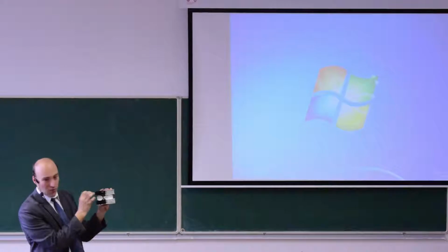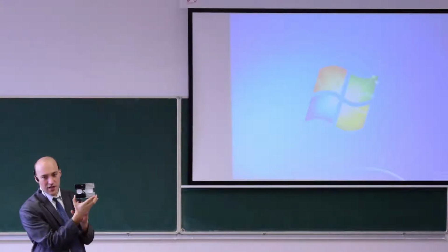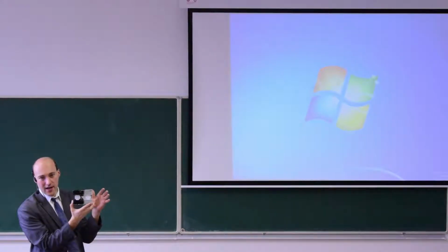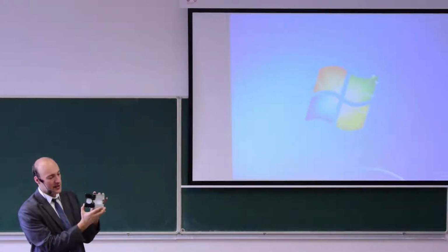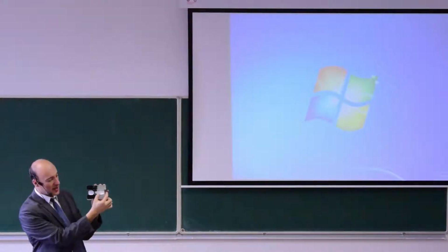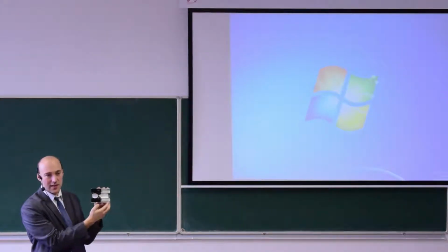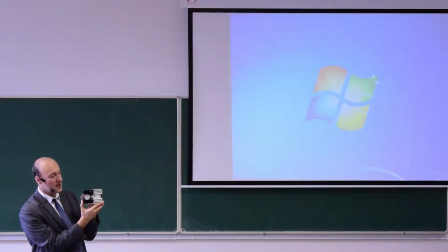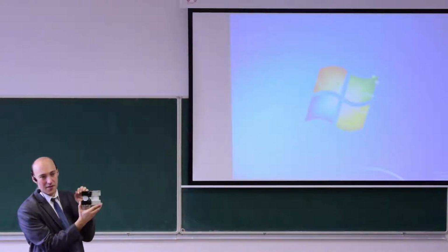If you look with a thermal camera at such a heat sink, when its temperature is higher than ambient, let's say 50 centigrade, you will see that here we have the 50 centigrade, but here on the aluminum surface, it appears like it has a low temperature, like 25 centigrade. And the reason is that we have a difference in emissivity.